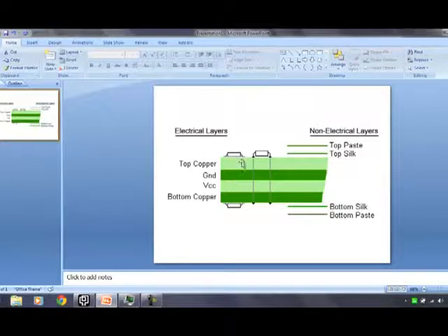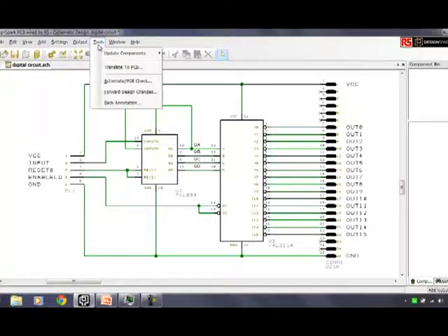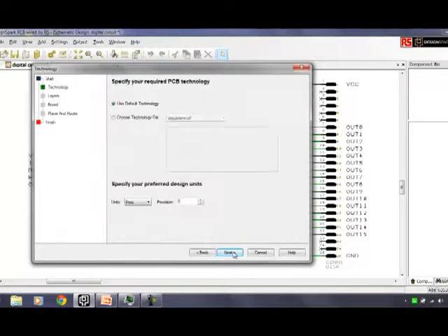So what we're going to look at today is how we take what we see as a simple two-sided board within DesignSpark PCB, and we're going to introduce extra layers which actually physically exist, sandwiched within a circuit board. So again, we're going to take a simple design here: the digital circuit with a connector, 2 integrated circuits and a plug. We're going to do a quick translation to PCB, and we're going to look to introduce board layers for the VCC and ground. So very quickly we're going to come to the translate to PCB, which I covered in the last video. I'll just rush through to where I want to be.